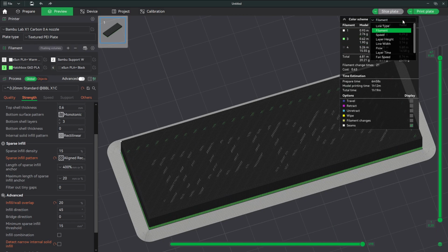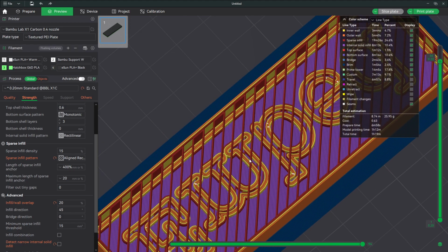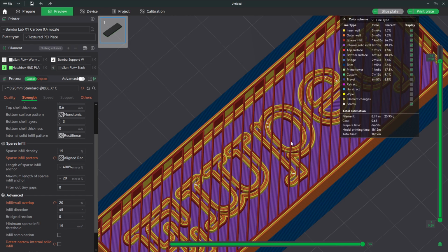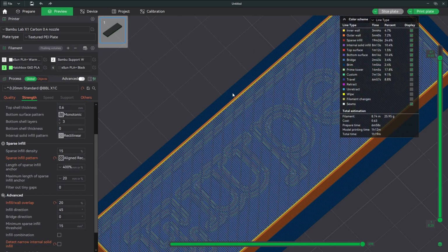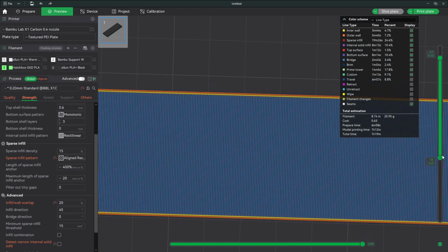And this is where having line type turned on helps. So you can see here it's printing at a 45-degree angle. My goal for my top surface is to have as small a gap as possible that it prints across. Now, my first top surface layer is considered a bridge because it's bridging across these items. I go up to that next layer. It's going to try and pick the shortest distance between walls, so it's going to be printed this direction. That's pretty decent. In fact, let me hide what's beneath it. You can see that red coming through there. Those are fairly small. I can make that better though.